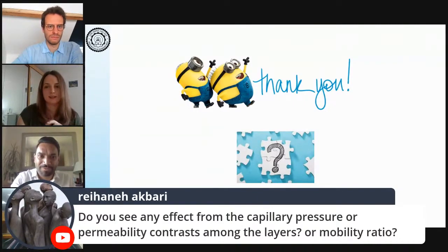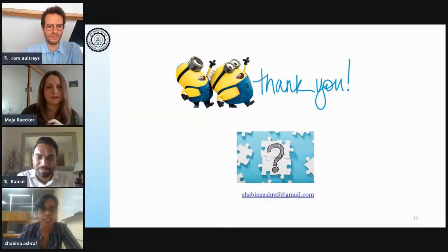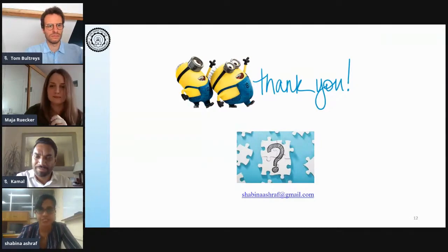Yes. The capillary pressure is inversely proportional to the bead diameter. That is roughly what we have taken from the literature studies. Otherwise, here instead of using small pores, medium pores, or large pores, in my publications I've mostly used the terms capillary pressure and permeability, because it would be complicated here. But yes, with the change in grain sizes, the permeability changes, the capillary pressure changes, and this one-dimensional model is very well applicable for mobility ratios of the order of 1 and 0. For high mobility ratios, I think the phenomena also change.